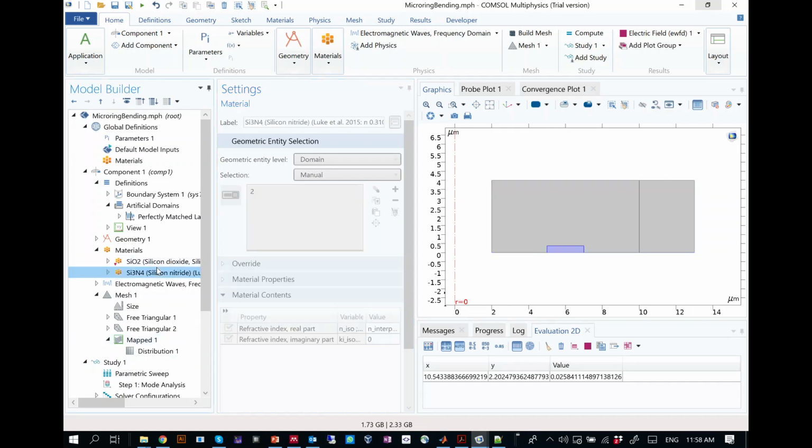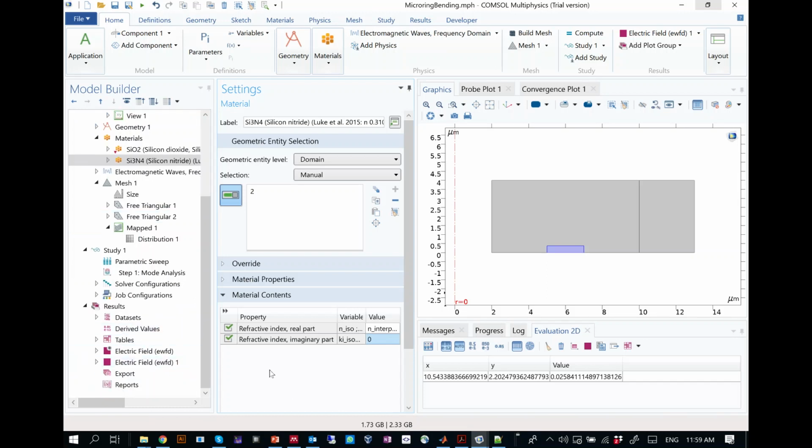It's not necessary to get sufficient results. So what I did here is I deleted the imaginary parts of the natural refractive indices. If the database has some absorption, because glass absorbs at low wavelengths, I don't pull it over to the model, and I only get the bending loss. That's interesting, to see the mode distribution in log scale. Yeah, true. I've put it here.